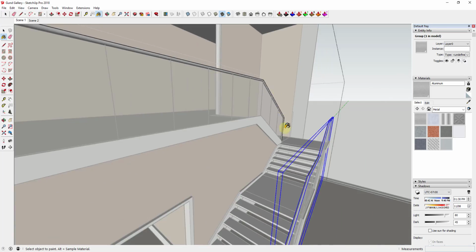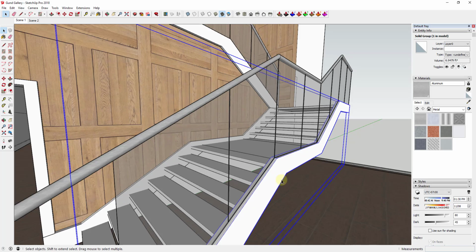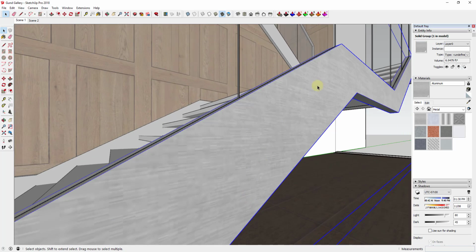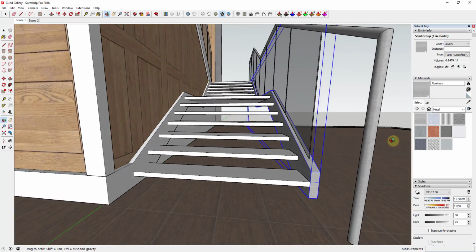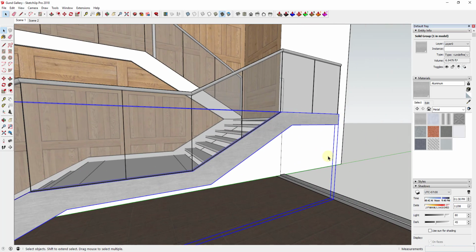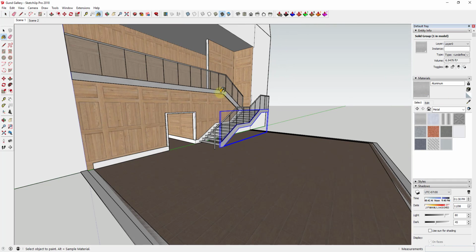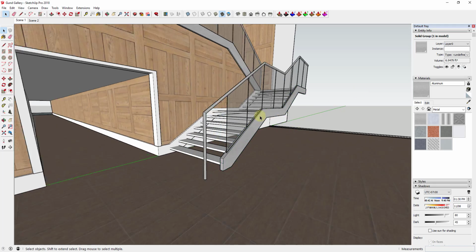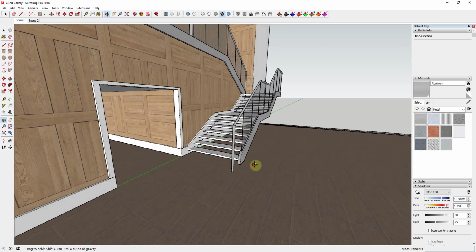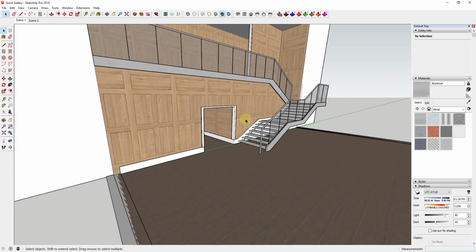I think that's going to look good. I may swap it out if I go into like Lumion or something like that. And I think we're also going to apply that to the exterior of this face right here, or this object right here. And again, just be careful of the way this is tiling on here, and make sure that you don't have a repetition of the same pattern over and over again, because that's not very realistic. The nice thing about this one is because it goes up and then across, even if you have tiling issues, it doesn't really look like much of a problem, just because you can't see the image tiling over and over again on each face.